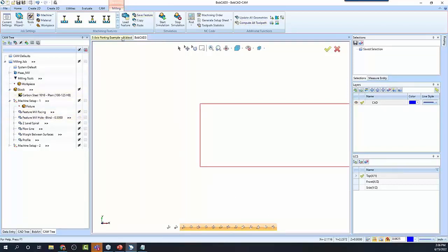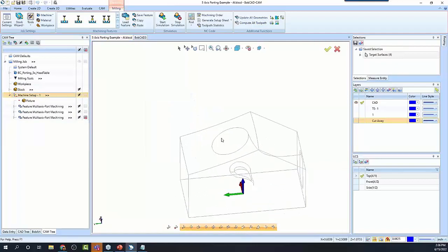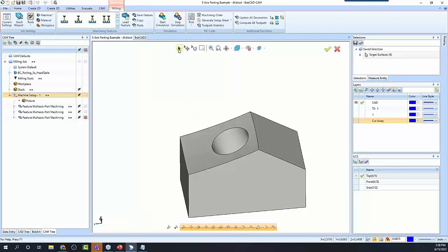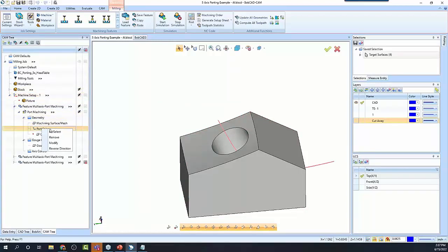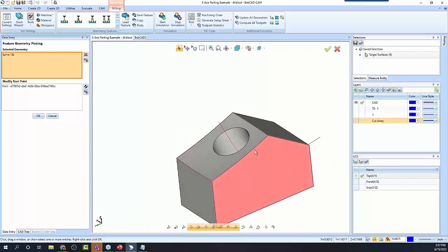The other thing about the CAD selection, again, we spent some time on this. When you're selecting edges for a routine, if you're working off a surface edge, you can right click and choose constant Z, and it will select everything that is coplanar to that. You can also right click and choose a loop selection. Just don't pick the same edge for that loop selection. That will help speed up some selections.